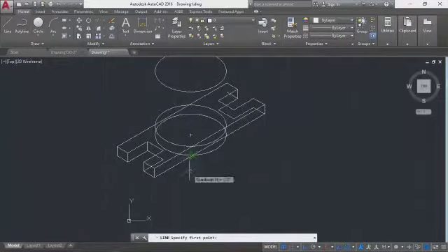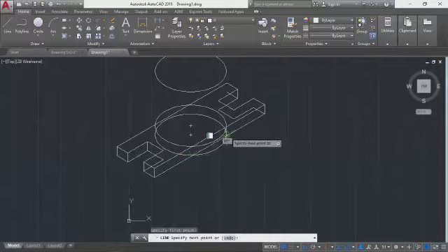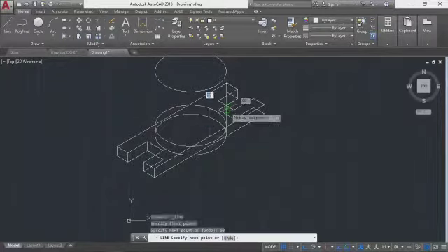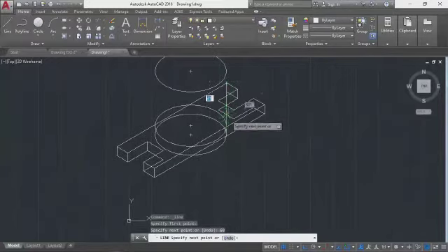You click, you see now, it's showing the intersect. Now you come over here, that is intersect. You click on it. You move it. Instead of moving it up, you can just type 60, because you have from that point to 60 up, enter. Ctrl Z.